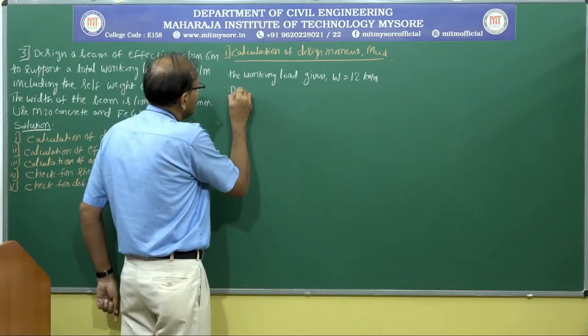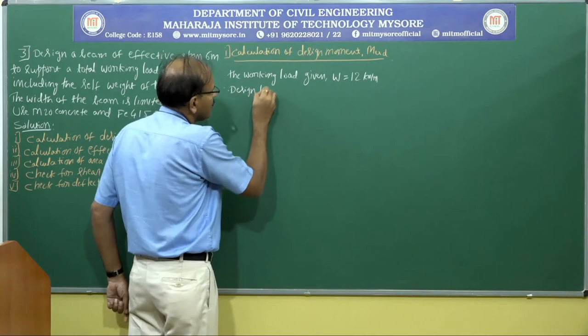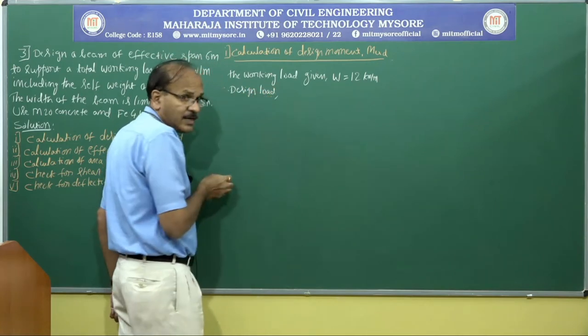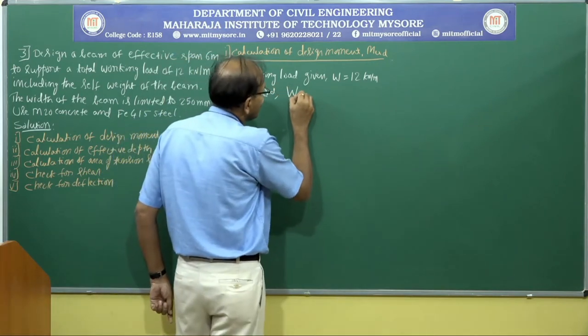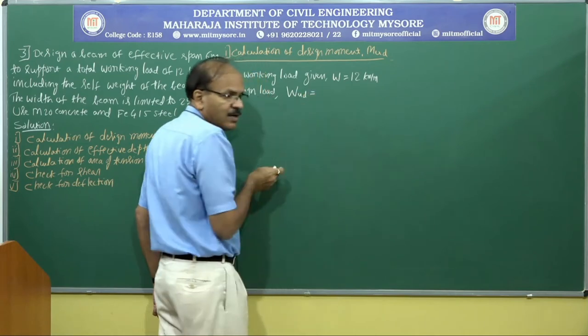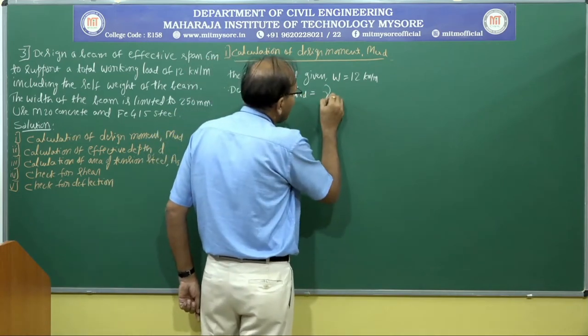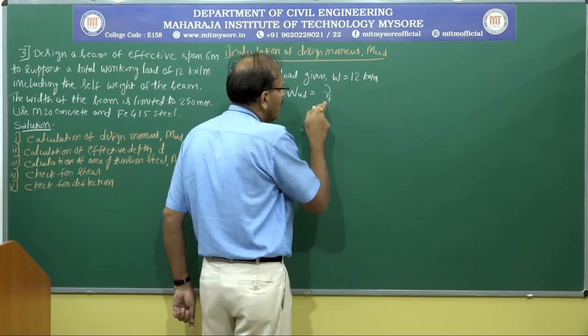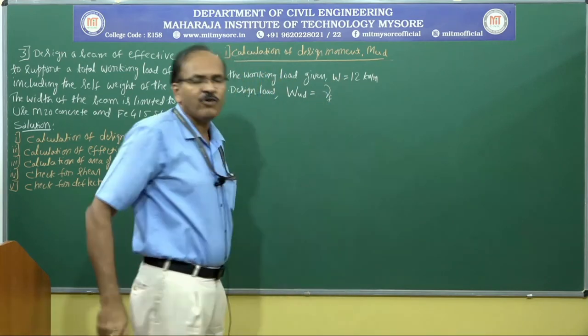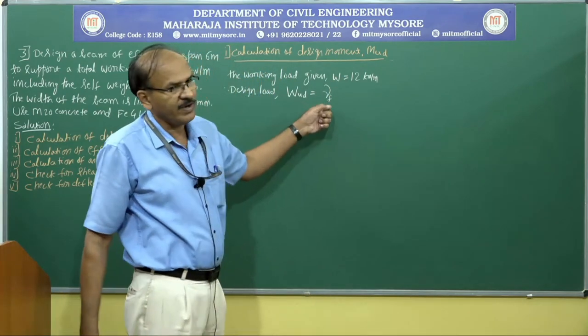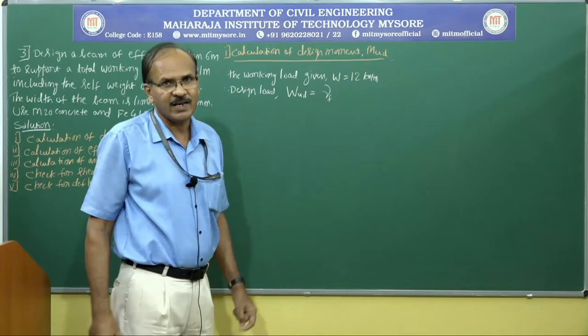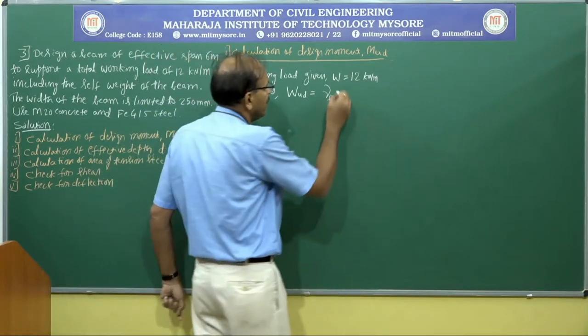Therefore, design load, I am going to call this as WUD. I am going to multiply W value with a load factor. What is the value of the load factor? That is 1.5, as we discussed in the previous example.